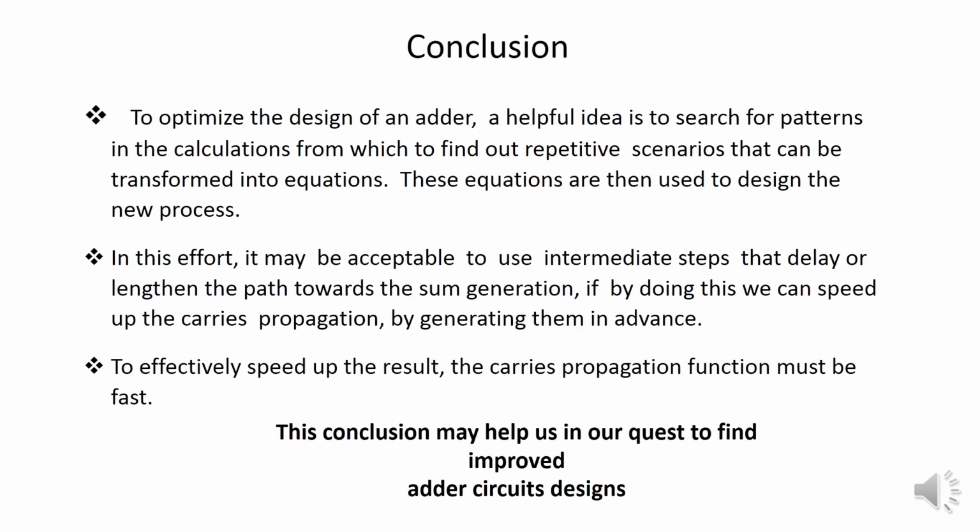So, in conclusion, to optimize the design of an adder, a helpful idea is to search for patterns in the calculations from which to find out repetitive scenarios that can be transformed into equations. These equations are then used to design the new process. In this effort, it may be acceptable to use intermediate steps that delay or lengthen the path towards the sum generation, if by doing this we can speed up the carries propagation by generating them in advance.